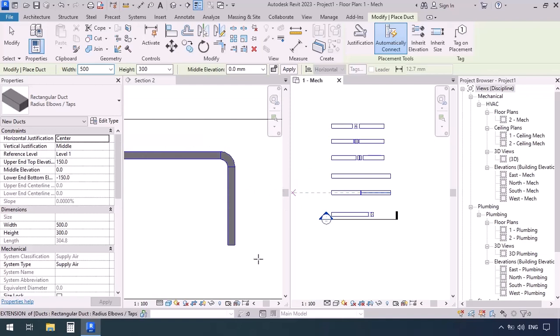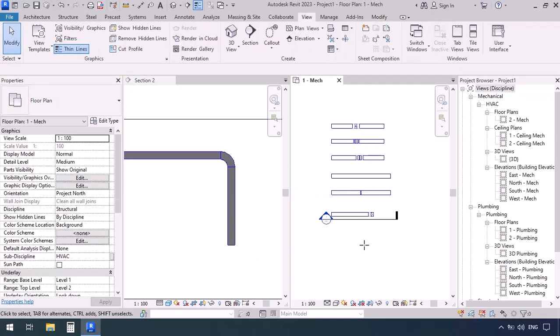For example, in case we want our duct to have a riser shape, we can use this method of changing elevations as well. As in, we wouldn't need to necessarily change the elevation and continue drawing the duct. Now, these points that we just mentioned about changing elevations are very useful for when you have a duct interfering with something else, or you have multiple items at once. Sometimes you might need to split your duct in order to solve that interference. You might even need to change the elevation of some other items.